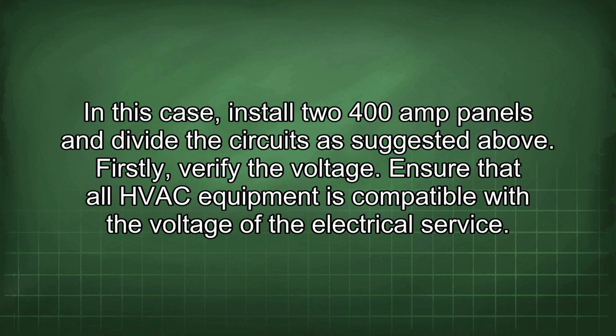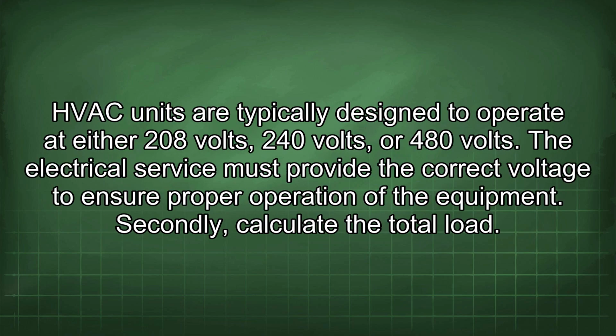Firstly, verify the voltage. Ensure that all HVAC equipment is compatible with the voltage of the electrical service. HVAC units are typically designed to operate at either 208 volts, 240 volts, or 480 volts. The electrical service must provide the correct voltage to ensure proper operation of the equipment.